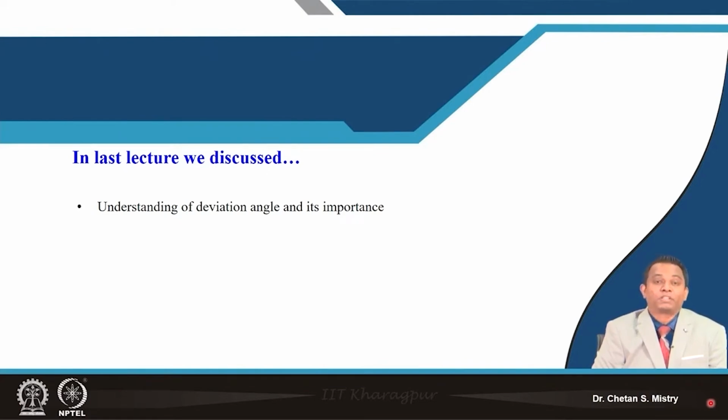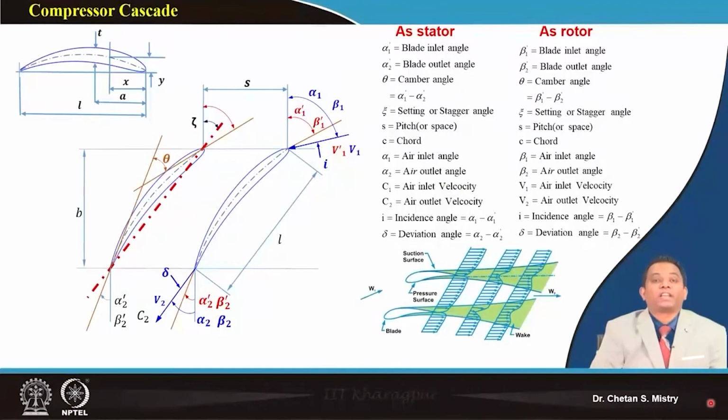We will discuss all this in detail when we discuss the design for a low speed compressor. We will discuss it for a high speed compressor, for a contra-rotating configuration, and equally for industrial fan design. But at this moment we can understand that we need to take care of the change of incidence angle and the change of deviation angle during the design stage only.